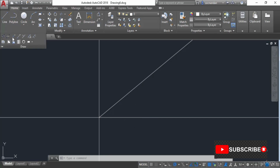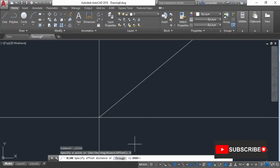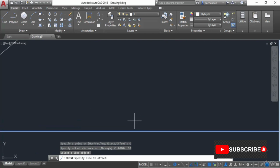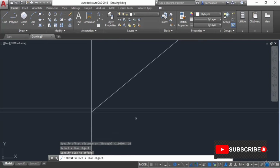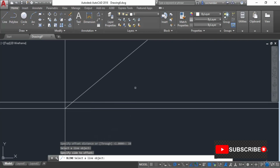So when you select the construction line tool, you'll see there is an option of offset. Selecting this option will allow you to create another construction line at a certain distance from the original one. So let's say that we want to make another construction line at a distance of 10 units. Let's type 10, press enter. Now select the first construction line and click on the direction in which you want to make another construction line. And here we have it. So now we have another construction line in the upper direction.